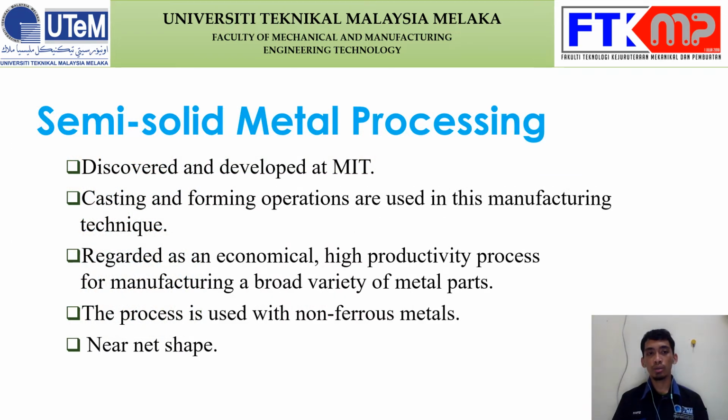Now, what is semi-solid metal processing? It was discovered and developed at MIT. SSM technology is divided into two categories, either from liquid alloy through controlled solidification under specific conditions, or from the solid state through heavy plastic deformation and recrystallization.